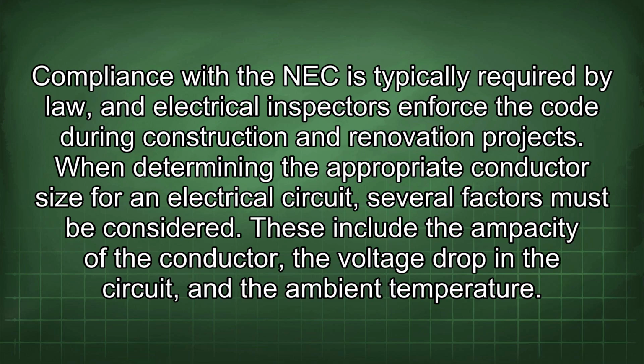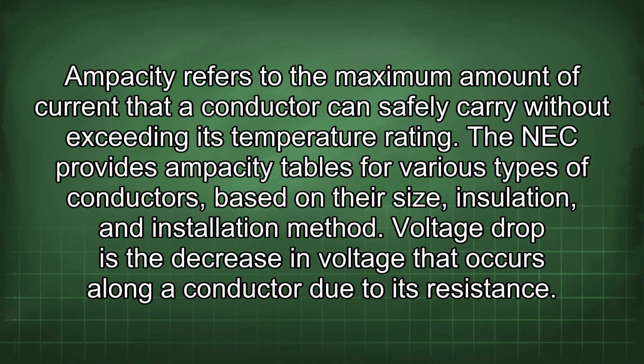When determining the appropriate conductor size for an electrical circuit, several factors must be considered. These include the ampacity of the conductor, the voltage drop in the circuit, and the ambient temperature. Ampacity refers to the maximum amount of current that a conductor can safely carry without exceeding its temperature rating. The NEC provides ampacity tables for various types of conductors based on their size, insulation, and installation method.